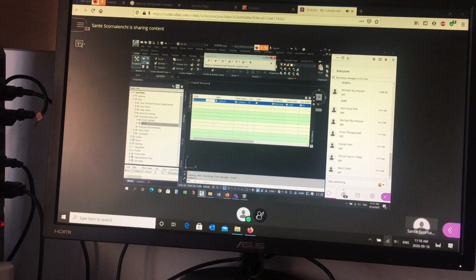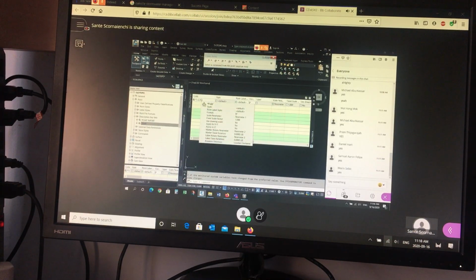New key. So what's the code? This is the text that's in the file. So remember T-centerline was one of the descriptions. Well, if I type the code, and then I put an asterisk at the beginning, an asterisk at the end, it'll capture any text string that has those 4 letters. And sometimes, I can't remember, each version changes a little bit. It may be case sensitive, so be careful, uppercase, lowercase. Okay? I believe all the descriptions in the file are uppercase. So that's the code. This is the description in the CSV file.